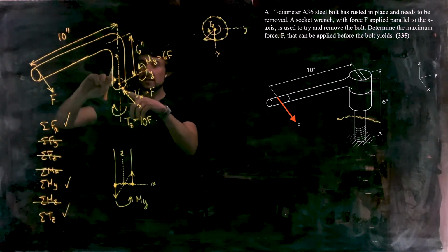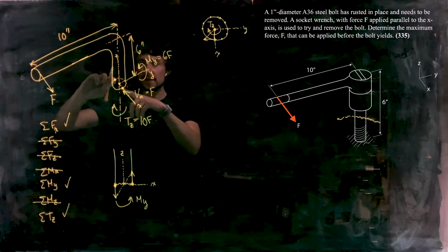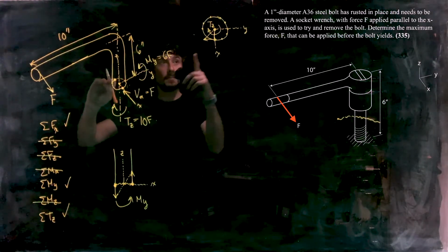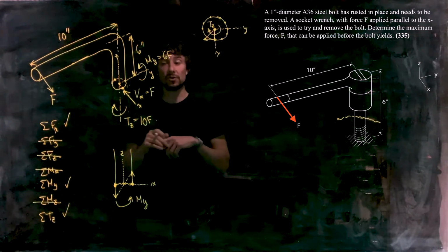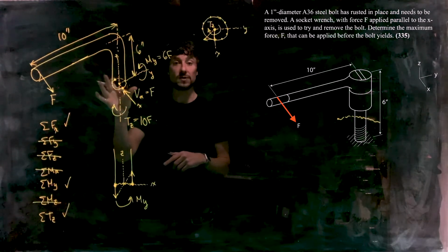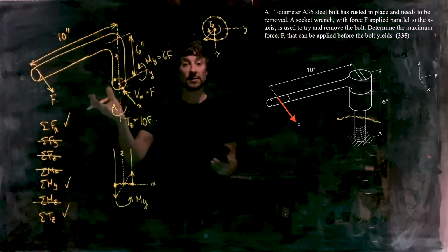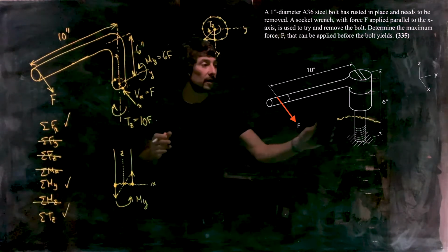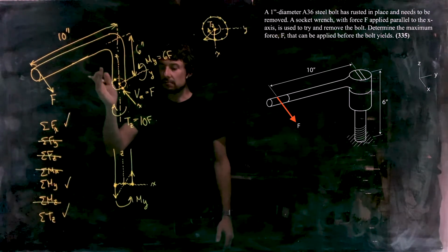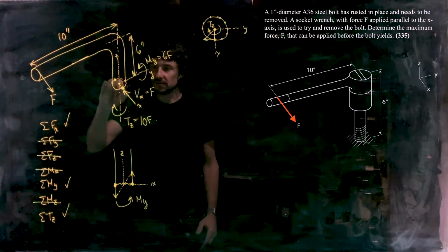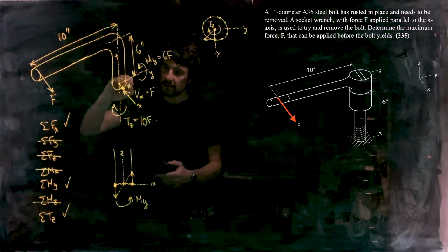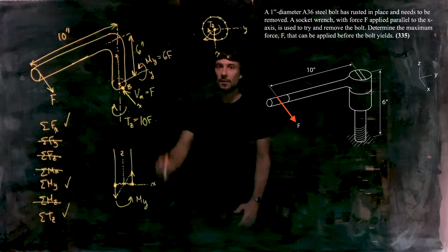Okay. So we've got 2 points here. Both those points experience maximum normal stress from the bending moment. Both those points would also experience maximum shear stress from the internal torque. So we want to choose one of those 2 points, and it doesn't matter which one we choose since the stress states will be equal. It's just one will have tensile stress on it and the other one will have compressive stress. So it doesn't matter which one we choose. Let's just choose this one here. Okay, so let's call this our point B there.